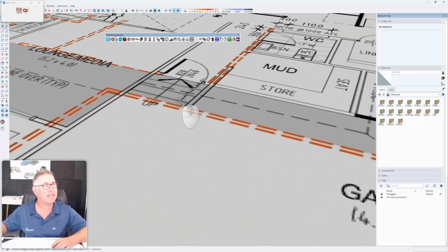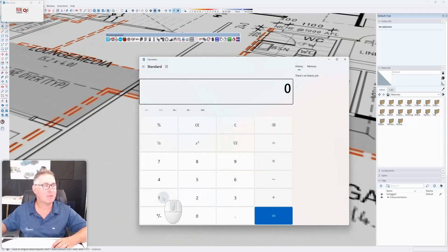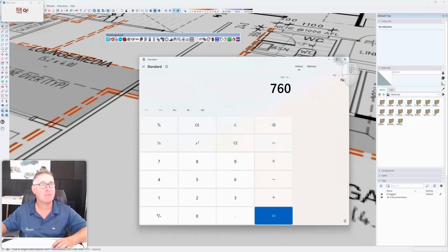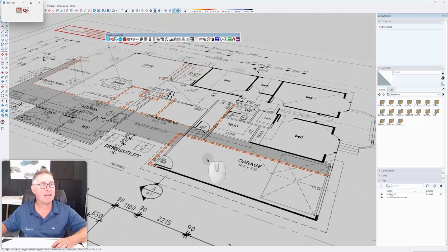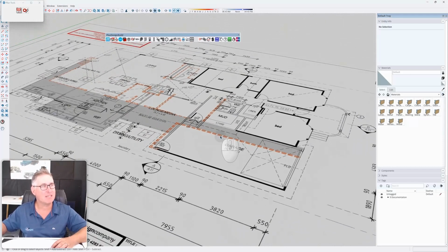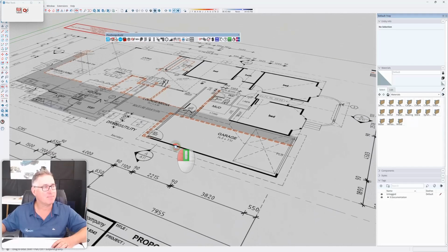You can see there's stairs, so therefore there's 1, 2, 3, 4 rises. So I've used my tape measure and put my maximum riser height because it's not written on the plan. So 190 times 4 equals 760. Right, so this plan steps down in this area. So I'm looking for stairs, therefore this is dropped down.